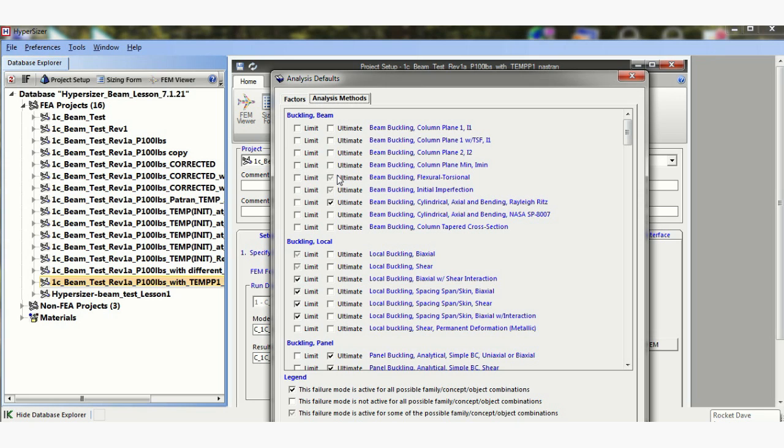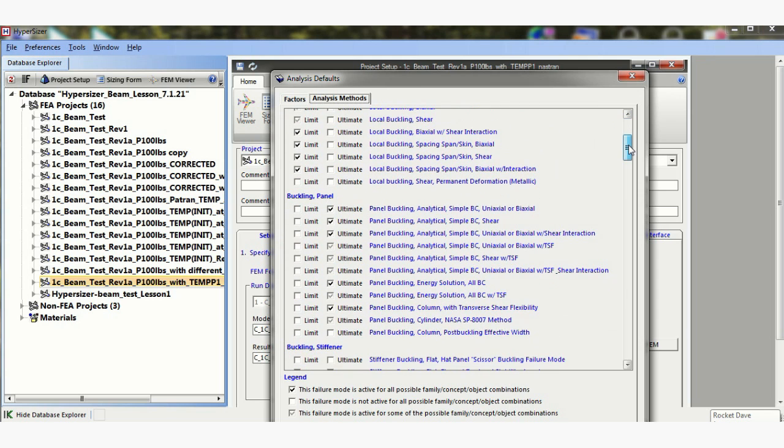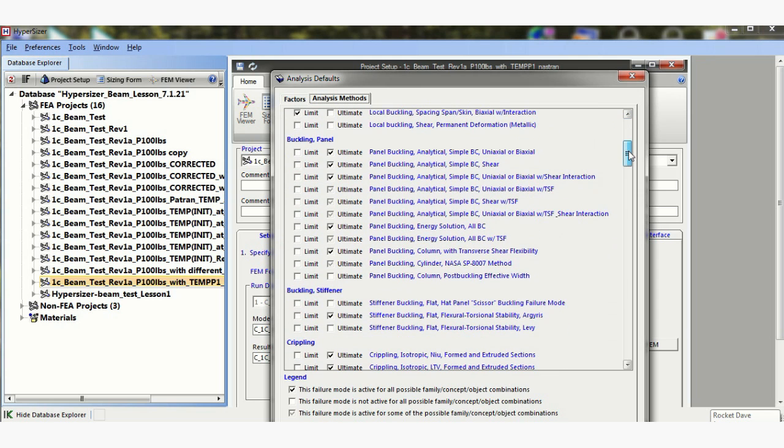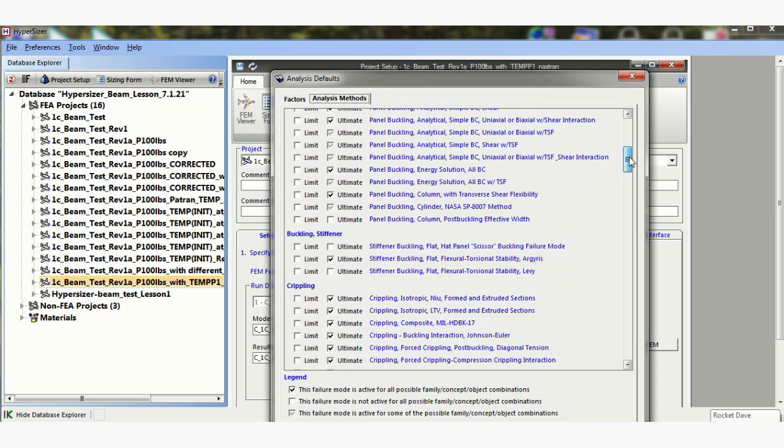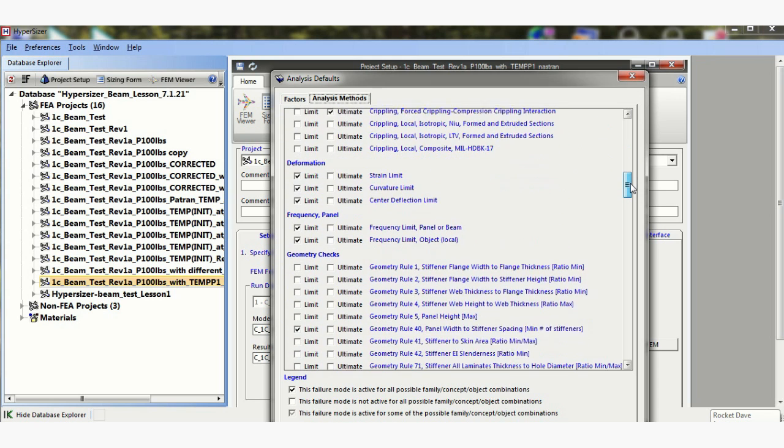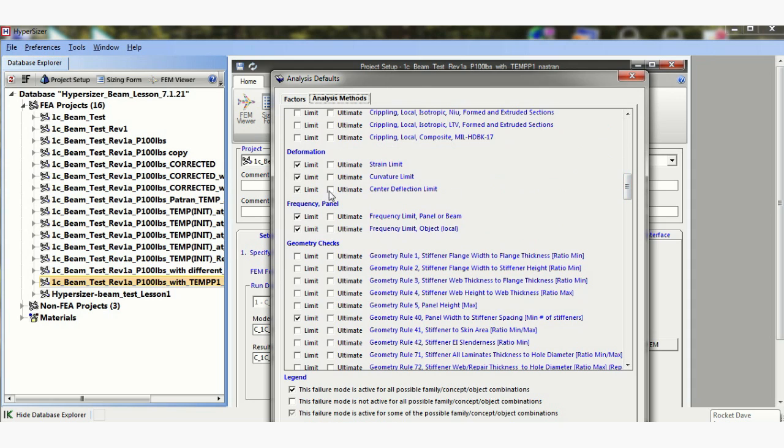And we can set up all of our analysis options here, which is our default analysis options that we wish to see when we boot up an empty database. So you would simply turn these on and off, whichever you wish, and save the empty database and move this to the template folder shown earlier on.